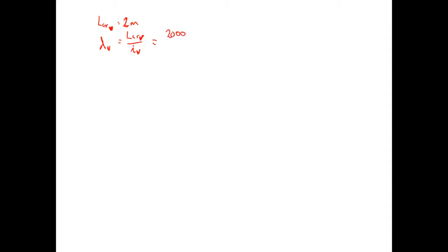So we're 2,000 millimeters again, 2 meters, and then from the blue book, we worked out that the radius of gyration is 15.5 millimeters. So when we work those out, we get 129 as being the slenderness value. Then the lambda bar is the slenderness value divided by the reference value, which is 129 divided by 93.9 epsilon, which is 0.92. So I get 1.48 for that.